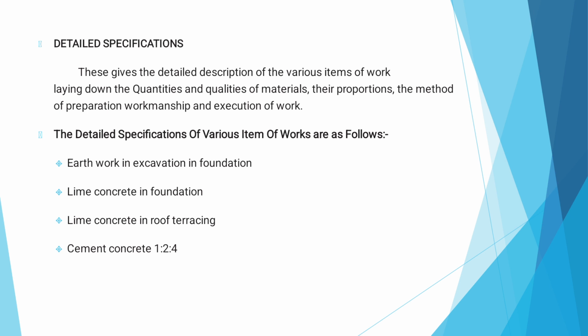Then second point, lime concrete in foundation. Lime concrete in foundation, first one is material. All material shall be as per standard specification. Then fine aggregate shall be surkhi or sand or cinder as specified. Then lime shall be white fat lime and shall be freshly burned and free from ash and other foreign matters. Okay. Then next, proportion.